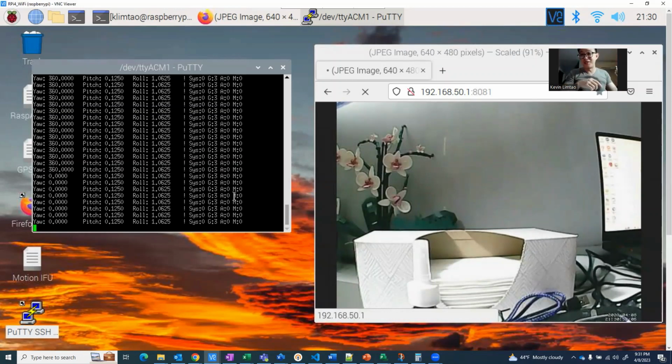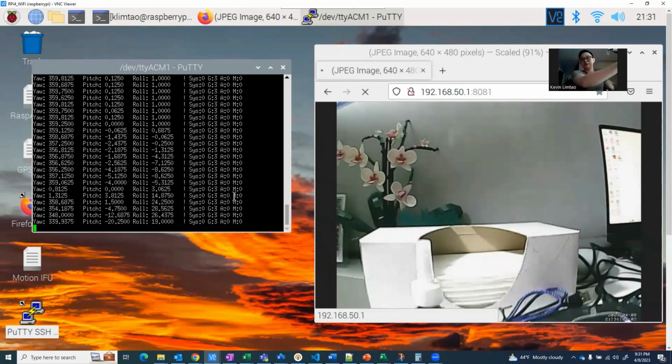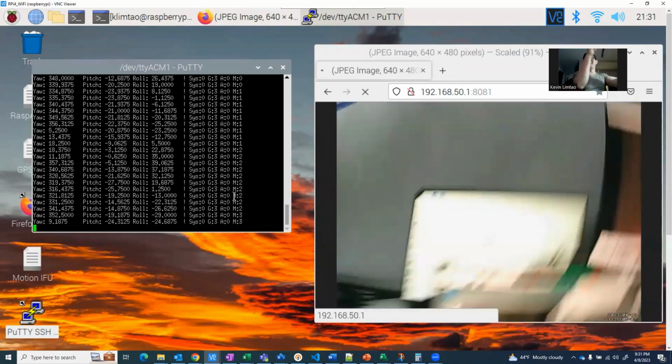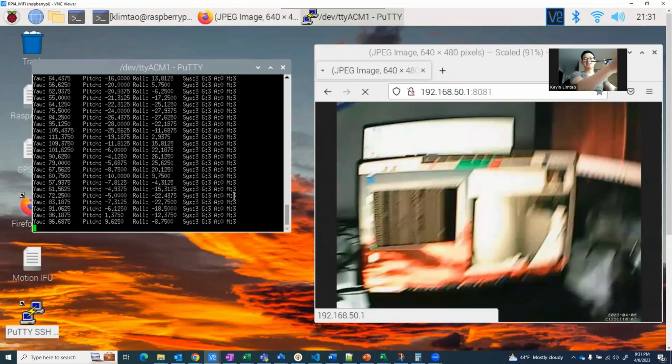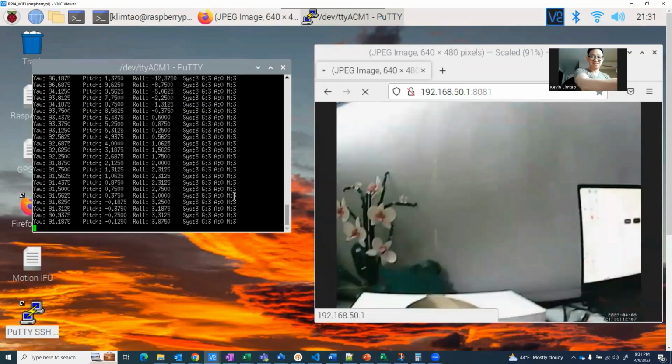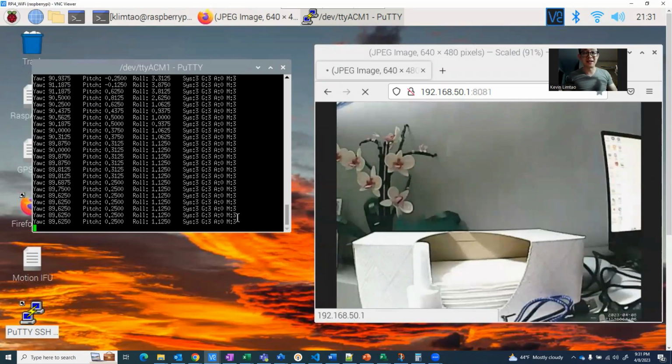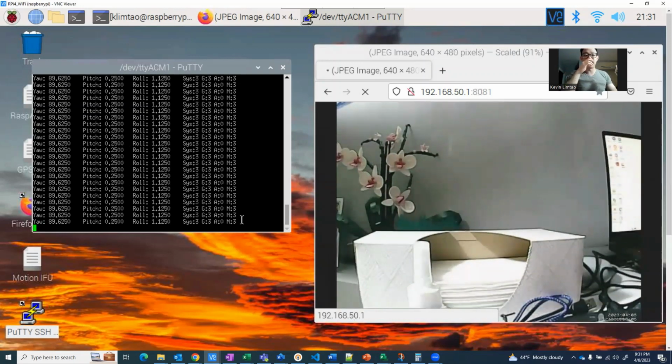And in the meanwhile, as I'm calibrating this, the webcam stream is going to fly around a little bit. So I'm going to try to calibrate the magnetometer just by throwing this around, and I have the magnetometer now calibrated. And actually, I'm not going to calibrate the accelerometer because it's a little more tricky to calibrate. I'm just going to leave it here, but demonstrate what the yaw, pitch, and roll measurements look like as I sit here.